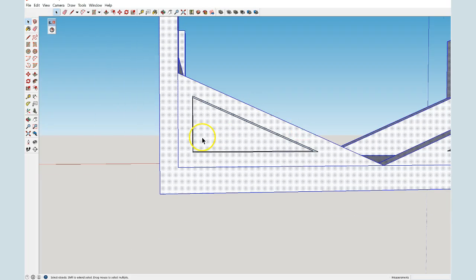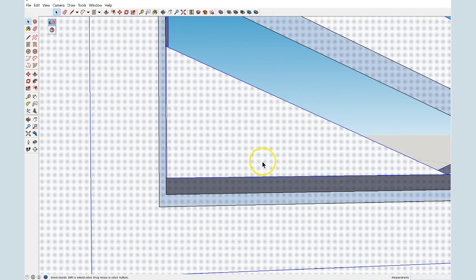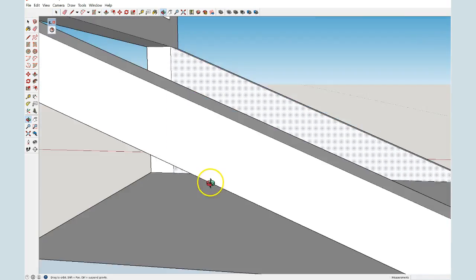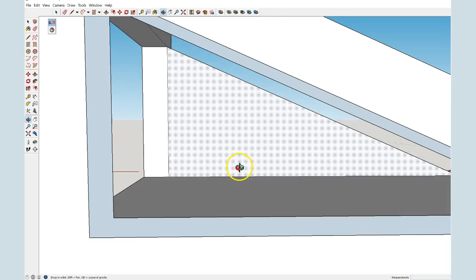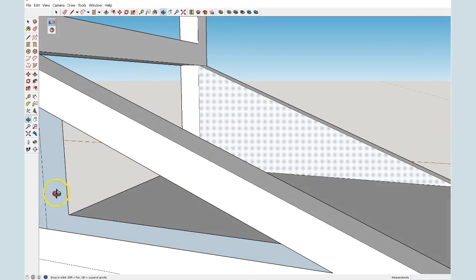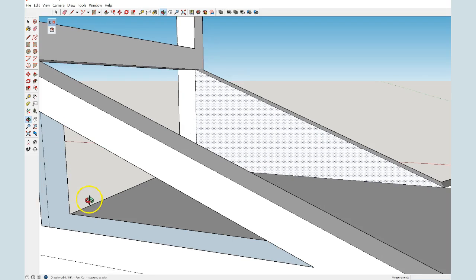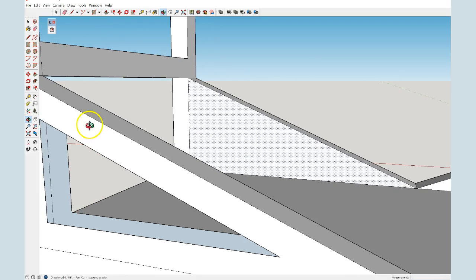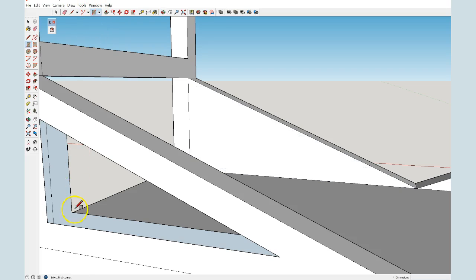So I'm going to undo that, and we can fix it manually because the tool doesn't fix it the way that we want. Okay, so basically the error is that this has no inside, and so it's a hole inside the solid, and so again it turned these edges into planes. So I can fill those by creating tops on them.